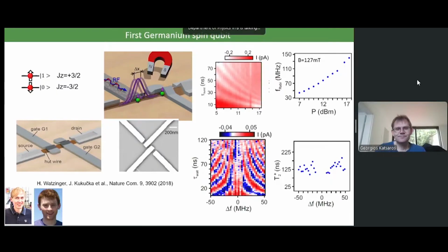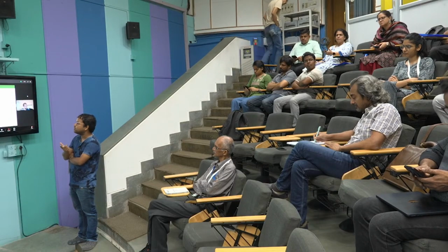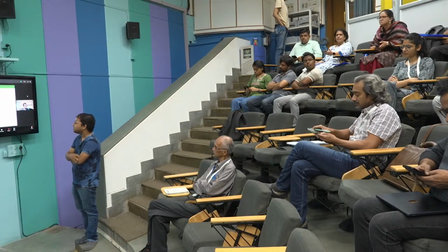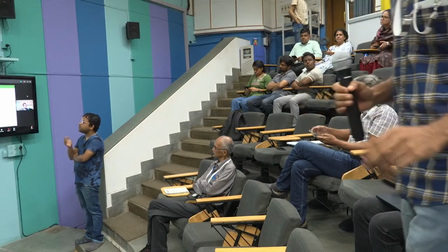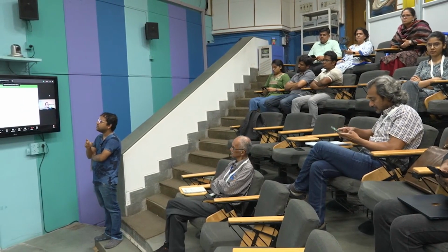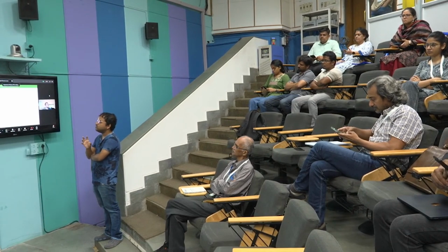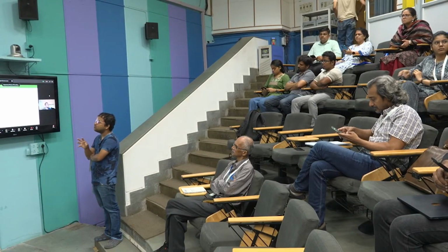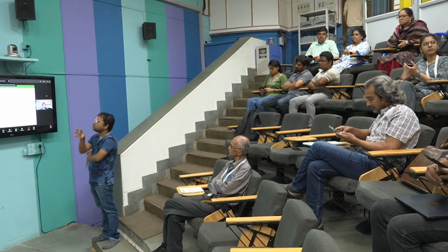I'll go then. In the last part of your talk, you said you can use, let's say, probably AI to choose the quantization axis of two different quantum dots, right? At this point, you would apply different gate voltages. That would necessarily limit you from controlling exchange or tunnel coupling, right? By choosing a quantization axis, you would be limited to one part of the exchange map.